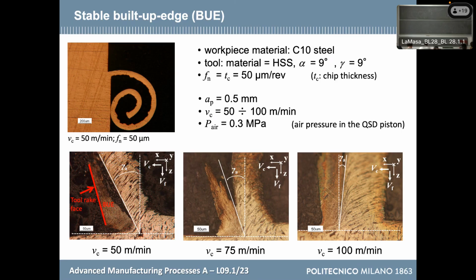They tell you that it is better that the cutting speed overcomes a certain minimum level. Otherwise, you have the built-up edge. But what happens in micro is that instead of removing the built-up edge, it stays there. These 3 slides, three pictures have been obtained with an increase in cutting speed, but it is still there.